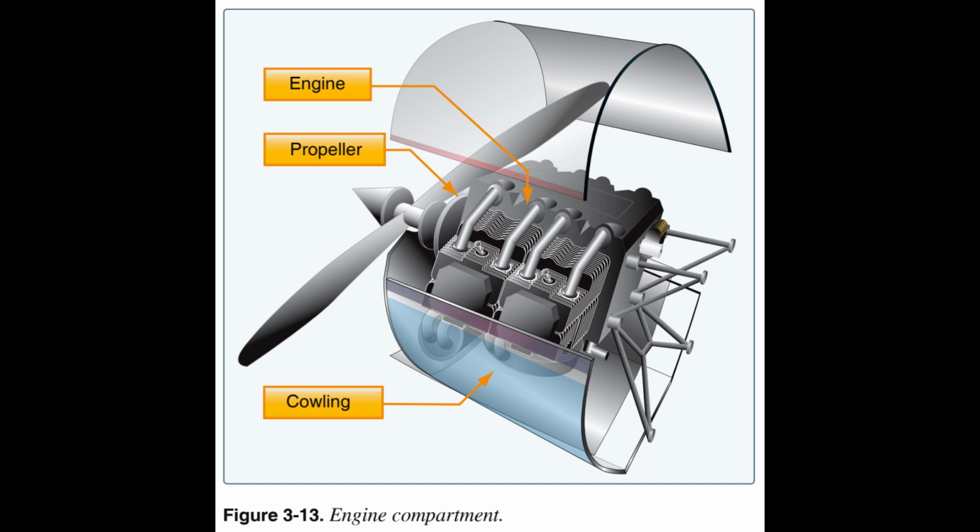The amount of lift being produced by the propeller is directly related to the AOA, which is the angle at which the relative wind meets the blade. The AOA continuously changes during the flight depending upon the direction of the aircraft. The pitch is defined as the distance a propeller would travel in 1 revolution if it were turning in a solid. These 2 factors combine to allow a measurement of the propeller's efficiency. Propellers are usually matched to a specific aircraft/power plant combination to achieve the best efficiency at a particular power setting, and they pull or push depending on how the engine is mounted.